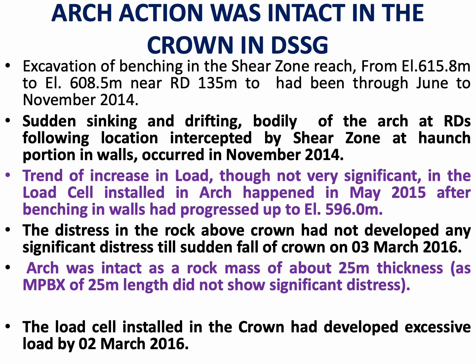Sudden sinking and bodily drifting of the arch at the following locations intercepted by the shear zone at haunch portions in the wall occurred in November 2014. As mentioned earlier, it was observed that the ribs had sunk in both the walls of the Downstream Surge Gallery in November 2014.